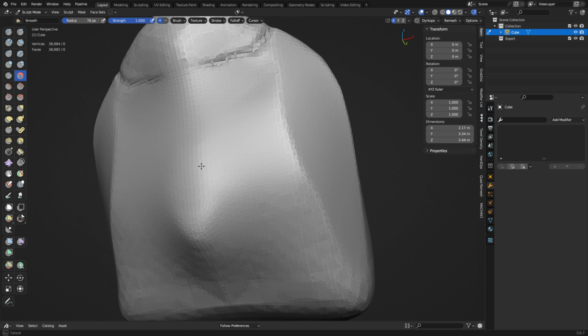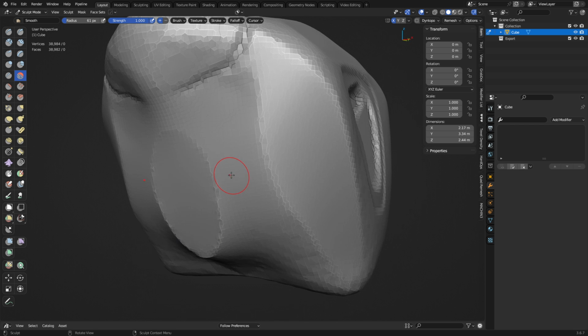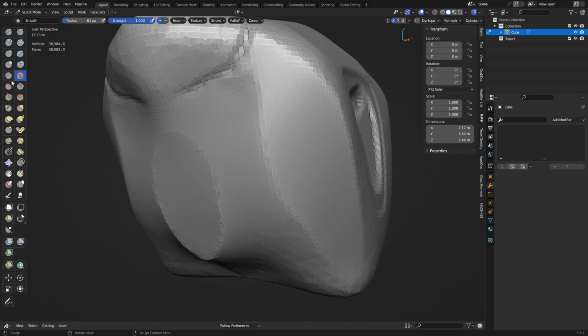If we work the smooth tool in an area with the falloff to constant, you can see it clearer. It is a Laplacian smooth, so it means it's flattening the normal underneath the brush. Okay, so it's actually a flattened brush, more or less. It behaves something like a sander would in real life. And as a result, you can actually use it in that manner right there.